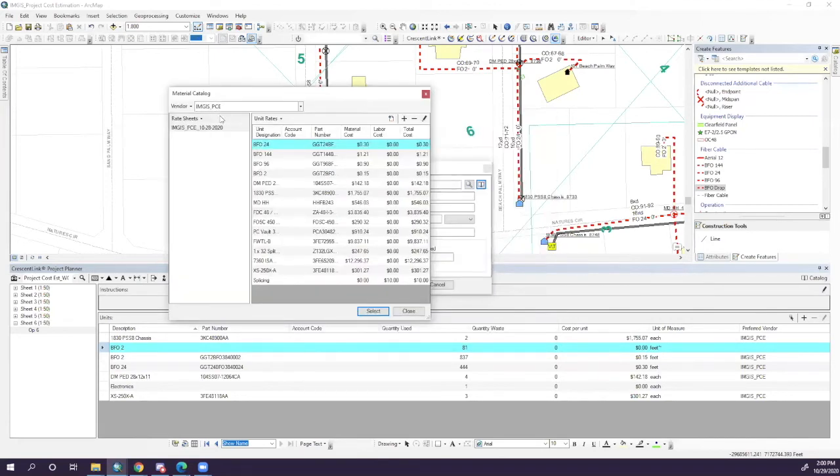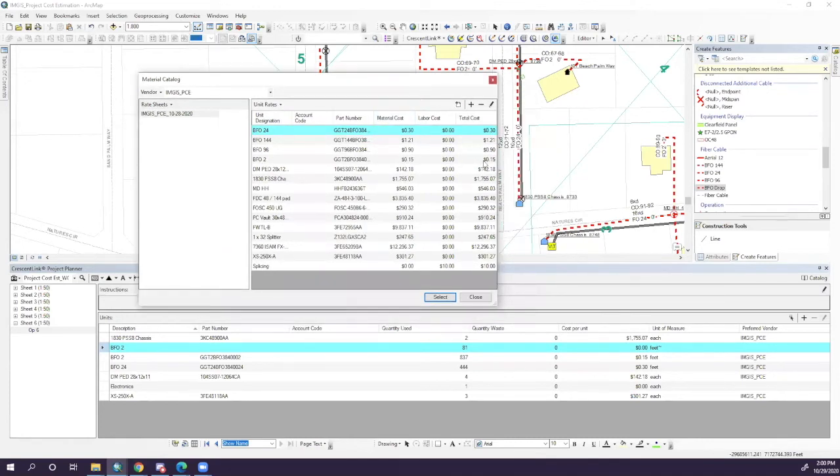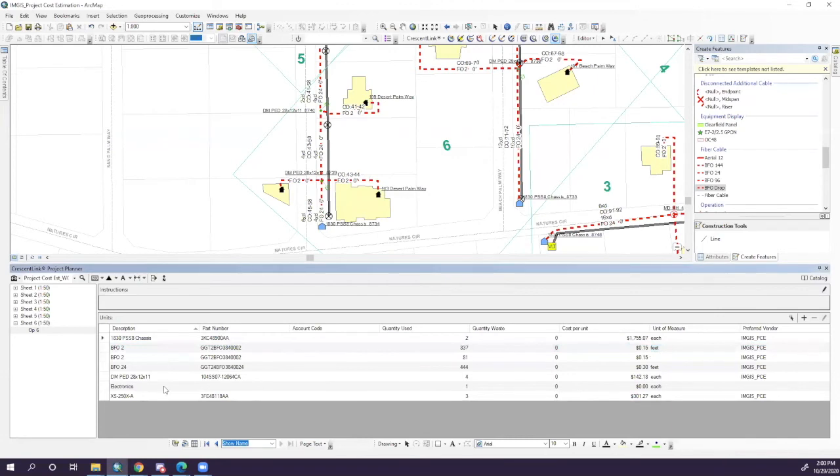I've just created a generic one for this specific project, but I see here I have my drop stored. I've got my part number associated with it, and I've got the cost associated with that material as well. I see it's costed by feet. So I'm going to click on this and apply it to this extra drop that I just added here, and you see it automatically populates that pertinent information. Okay, click OK. That's going to bring it on.